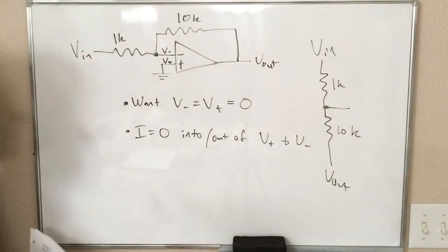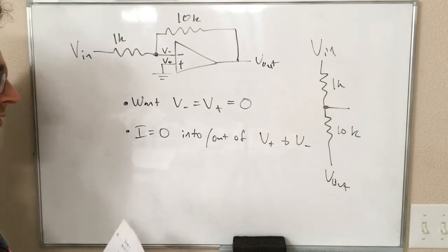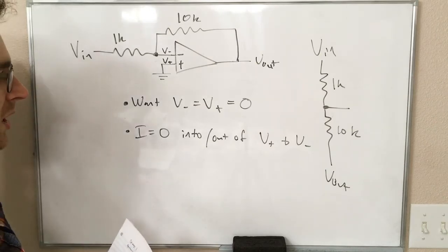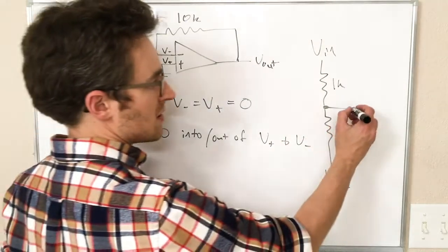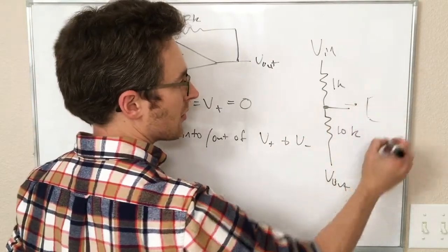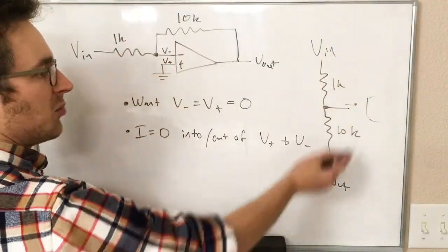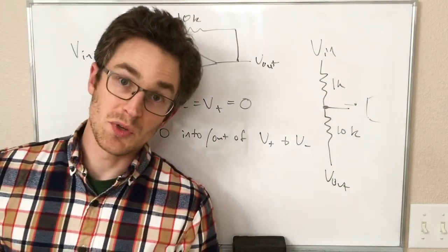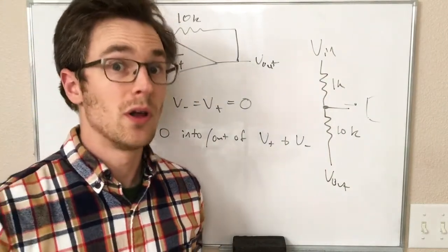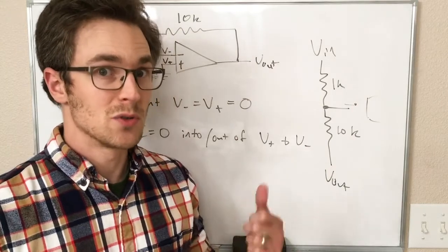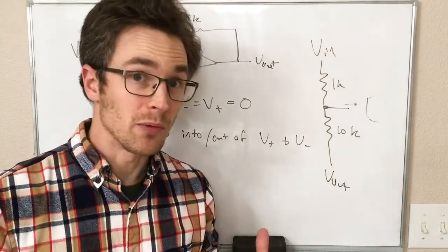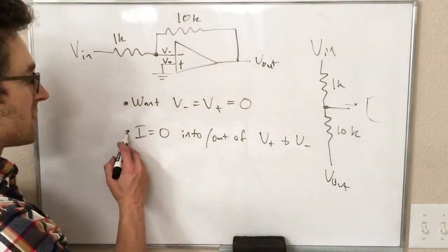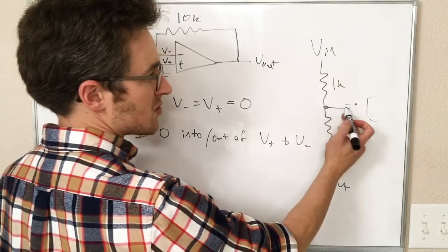As I mentioned when I talked about the golden rules a moment ago, if we just had something that looks like this and this went over to some other unknown component, we would not necessarily be able to use the voltage divider equation, because the voltage divider equation only works for things in series with nothing connected between them. However, the golden rule is telling us that the current equals 0 in this part of the wire.